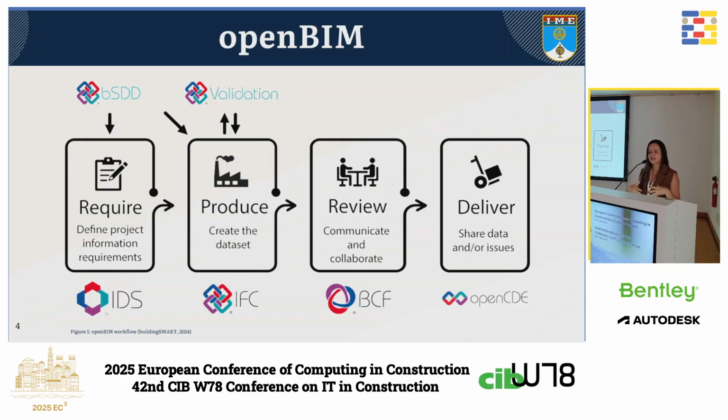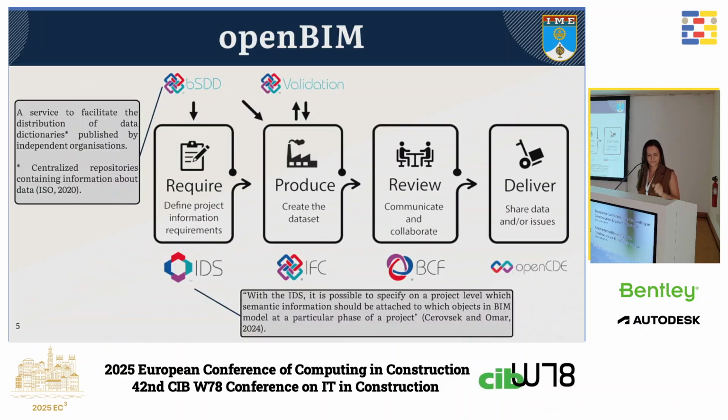Then, human and design tools create the data set and it can be stored in a file based on IFC schema. All of this with the complement of the bSDD service and IFC validation. Then, during the exchange process, we can communicate and collaborate using BIM Collaboration Format standards, and everything can be managed within a common data environment, a CDE.